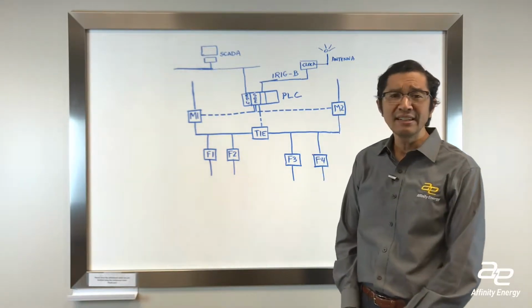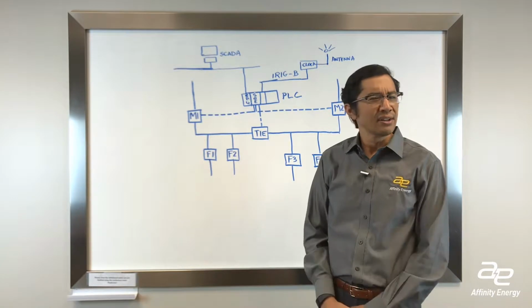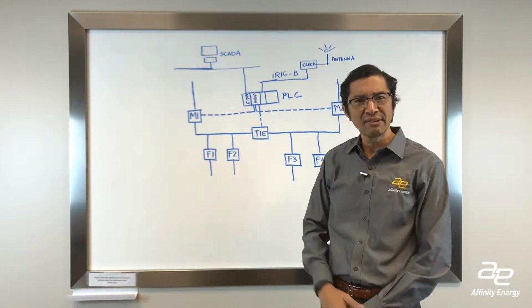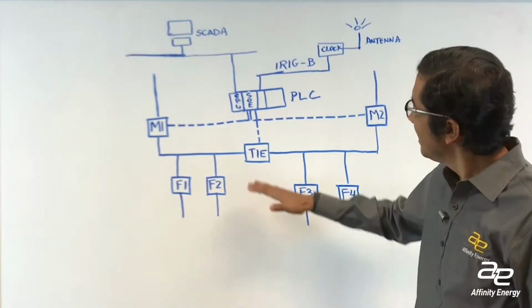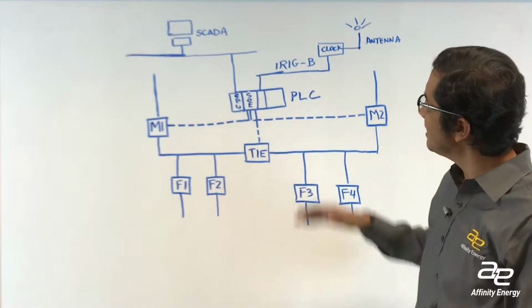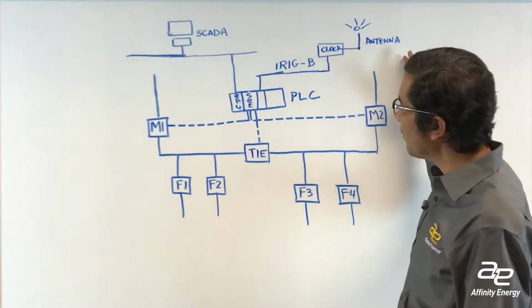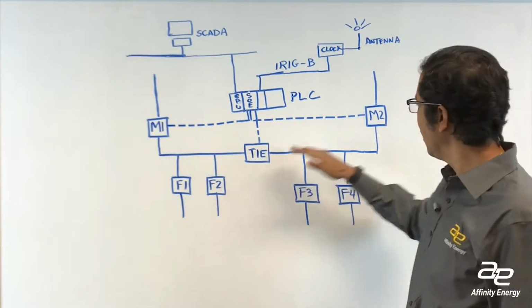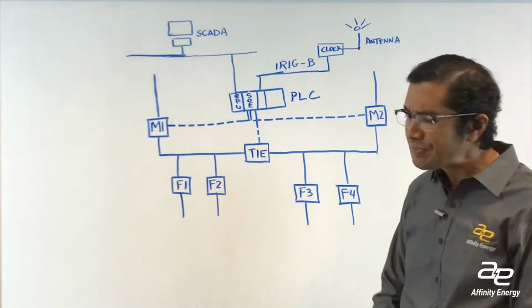Well, time synchronization is most important when it comes to root causing or diagnosing a problem that you might have with the controls or the hardware that is being controlled. For example, in this particular scenario, this PLC is responsible for detecting the presence of power upstream and then determining when to open and close certain breakers to make sure that power continues to flow downstream.